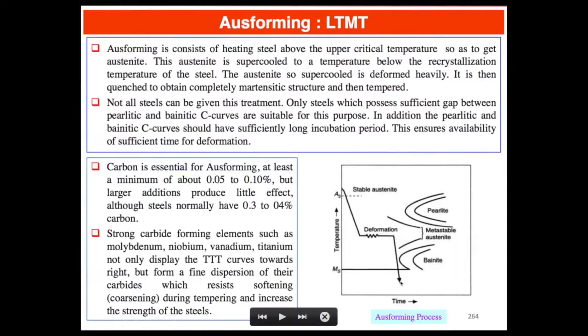And so we quench down, and we're fully martensitic. But what's the point of doing this forming process here? I realize it might be kind of silly to ask this question when the notes are up here and everyone has it. But we put in a whole bunch of dislocations. What likes to nucleate at dislocations heterogeneously?